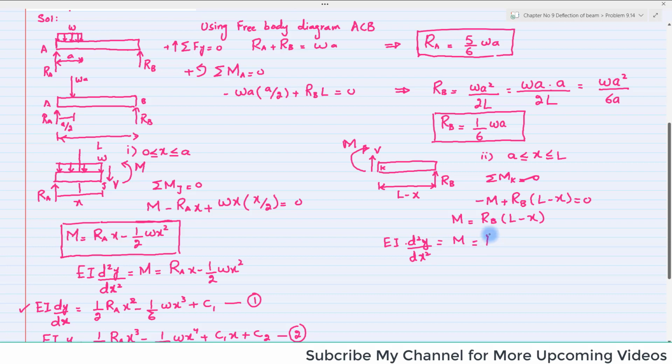So M is equal to RB into L minus x. If you integrate it for the first time, you will get EI dy by dx equal to minus 1 over 2 RB into L minus x whole square. Clear?